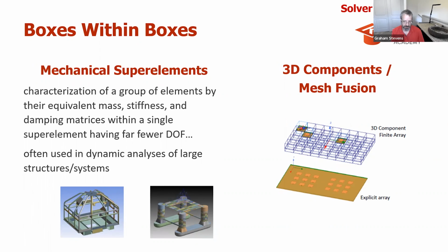And then Mesh Fusion takes that to another level, essentially, and allows you to mix and match the micro to the macro. So if I have small components inside larger assemblies, it allows those meshes to fuse and be valid and used. So it allows you to solve new kinds of things, and sometimes it's faster and sometimes it's slower.